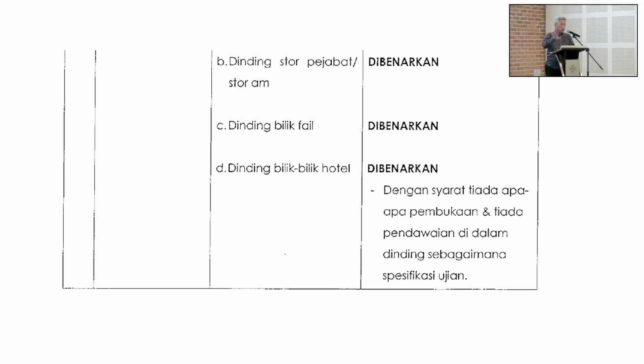But they also recognize that if you have a filing room and all that, because these things don't require fire rating, they need separation. If it's within the purpose group of the office, or we call it low risk storage where you're storing stationery and all that, have a fire rated partition in there. Or a computer room, for example. Most of the time when we have computer rooms, we ourselves want to do the fire suppression systems, so we will have to have fire rated. Bomba said that is your own risk, your own requirements. Go ahead, use dry walls. There are no limits to that.